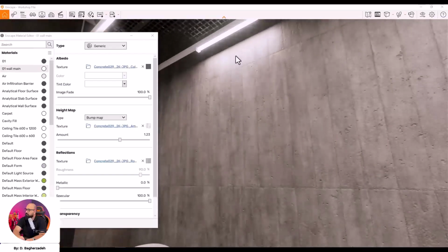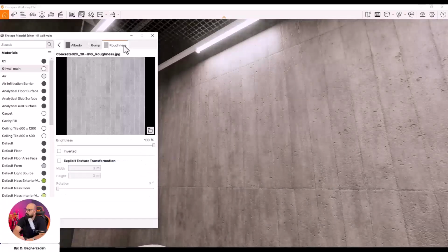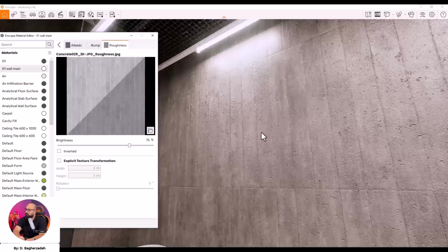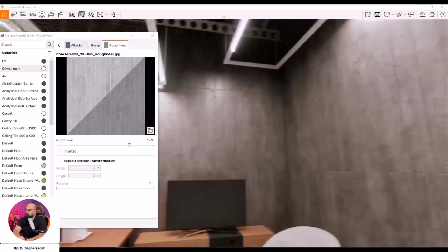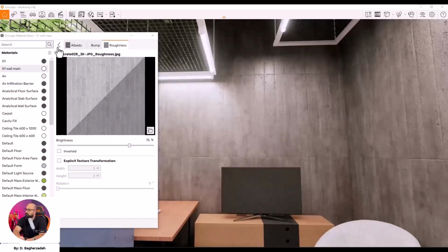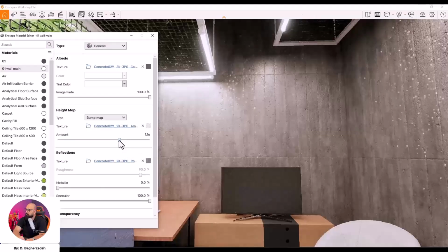And if you wanted to add more translucency, you can open up the texture here and then reduce the brightness all the way to the point that you'll get the exact amount of translucency and brightness that you want. Like, to be honest, this works actually. Yeah, we have a good amount of light reflection here. And you know what? Let's go one step further. Let's try to make everything more realistic.